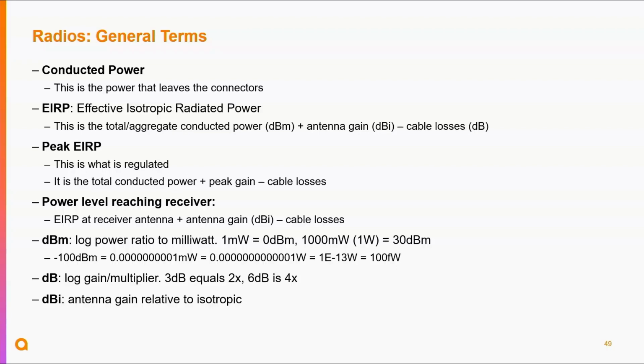But keep in mind again that energy, that 3 dB gain, is in a particular direction in 3-dimensional space. So you say, okay, I have an AP that has 3 dBi antenna gain. It must give me better performance than this other AP that only has 1 dBi antenna gain. That may be, but it's not necessarily true. If that antenna gain is pointing up at the ceiling, if your peak is in that direction, it doesn't matter, right? So the patterns are critical as well. I guess you already know all this, right? How dBs work and logarithmic, and so a lot of zeros there.